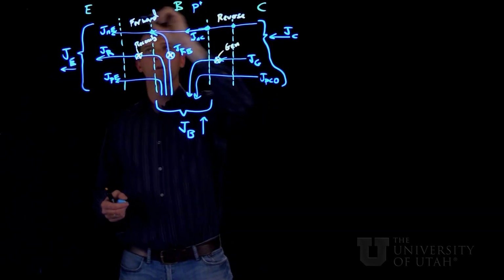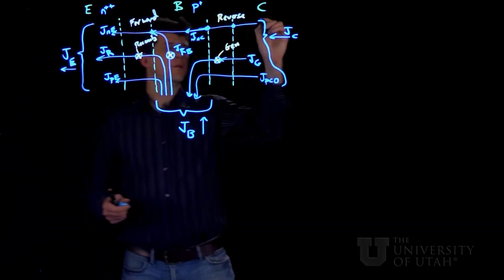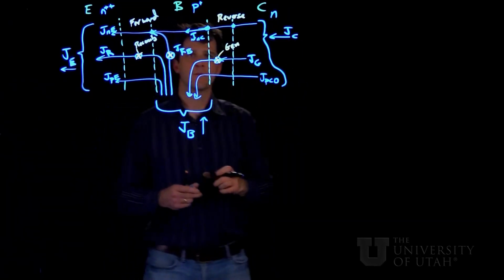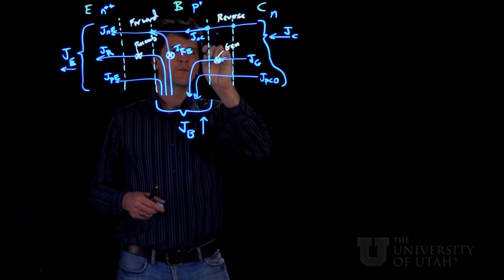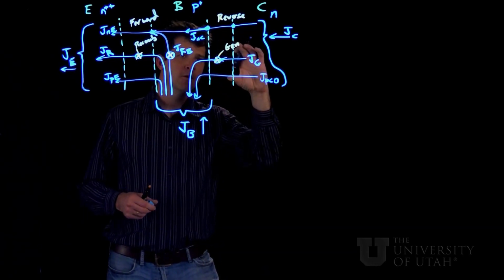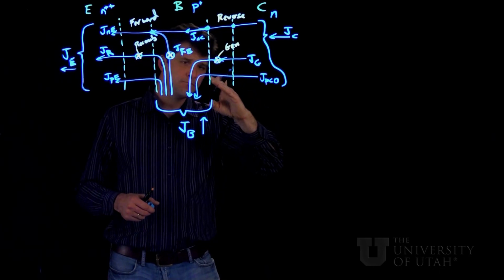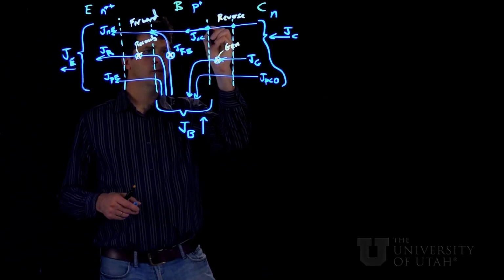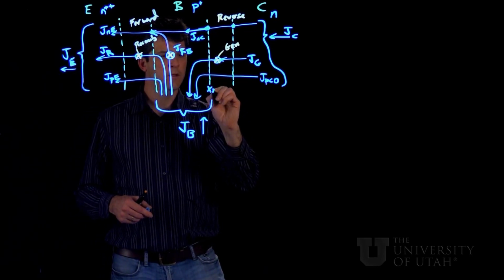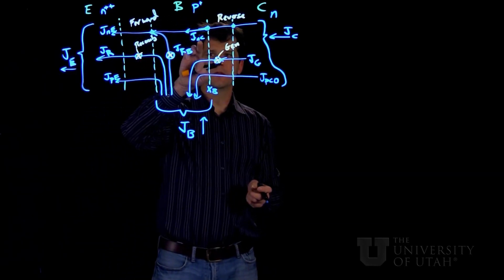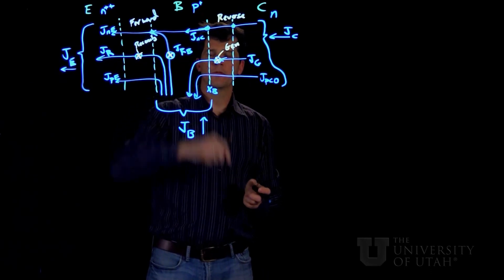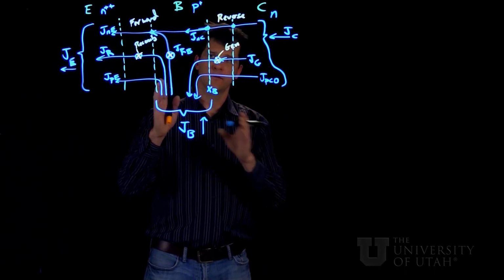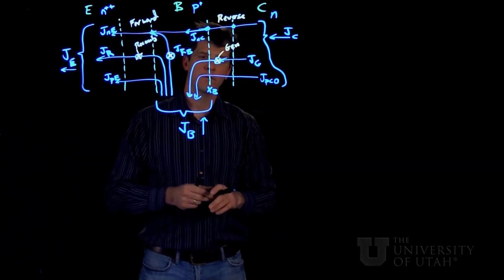So this is again our P plus and N plus plus regions. Right here at the edge of this depletion width, we have the current which is due to electrons injected into the depletion width, evaluated right here at XB. It's the diffusion current due to the minority carrier distribution that we just derived inside the base.